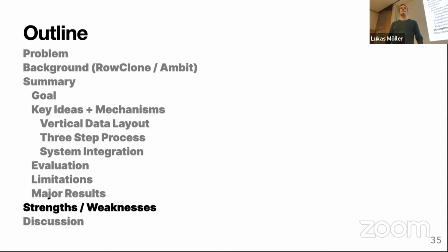Okay, so you have to specify in advance when you allocate the memory. You have to specify if it's vertically or horizontally. No, because the CPU always wants horizontally laid out memory, and for SIMDRAM we always want vertically laid out memory. So we just tell SIMDRAM, like the control unit, that we should lay that out for SIMDRAM, and then it will do that transformation whenever needed.